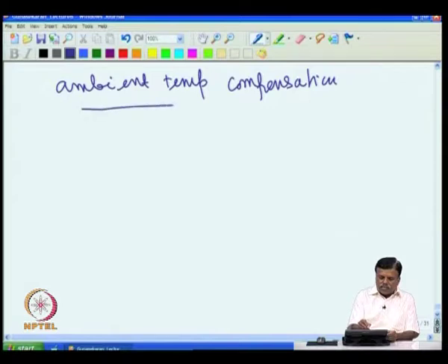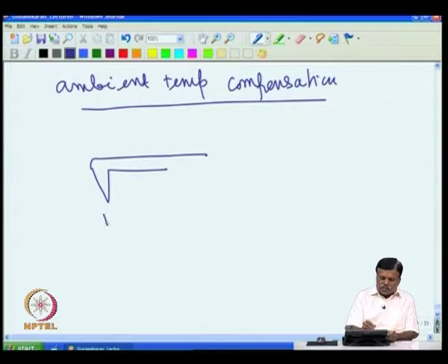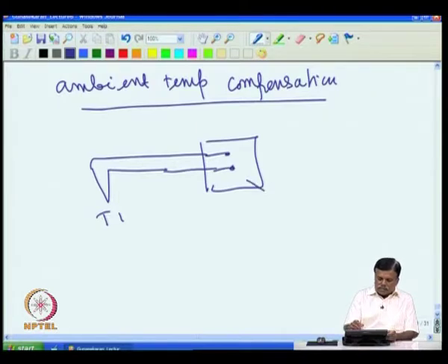So, what is done in this case is that you take the junction, keep it wherever the temperature is to be measured, say T, and then the thermocouple is terminated in an isothermal block, say copper, with of course insulation so that it cannot get shorted. So, this is at T ambient. Then you measure this temperature using another sensor, say like our IC sensor, for which I give plus 15 volt here.